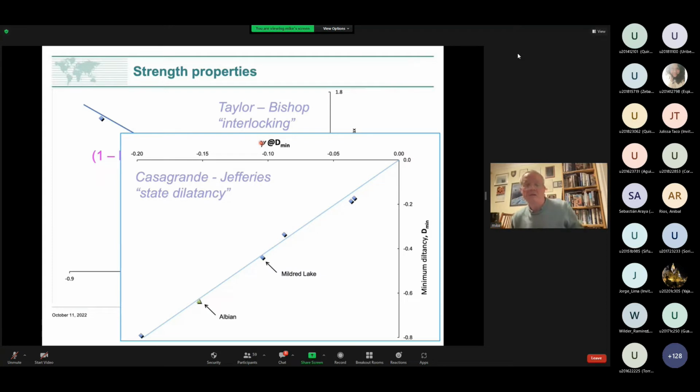It was convenient in the lab, convenient for plotting data, but it's actually not appropriate mathematically when you start pulling stress-strain behavior together. You need to work with a current value. So this becomes the state parameter at the maximum or minimum dilatancy, and you get a straight line. And the property chi is simply the gradient of that line.